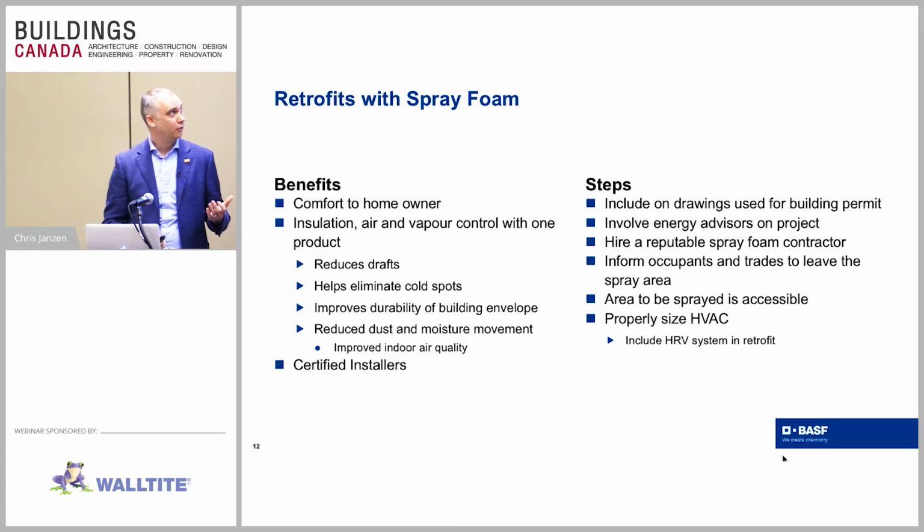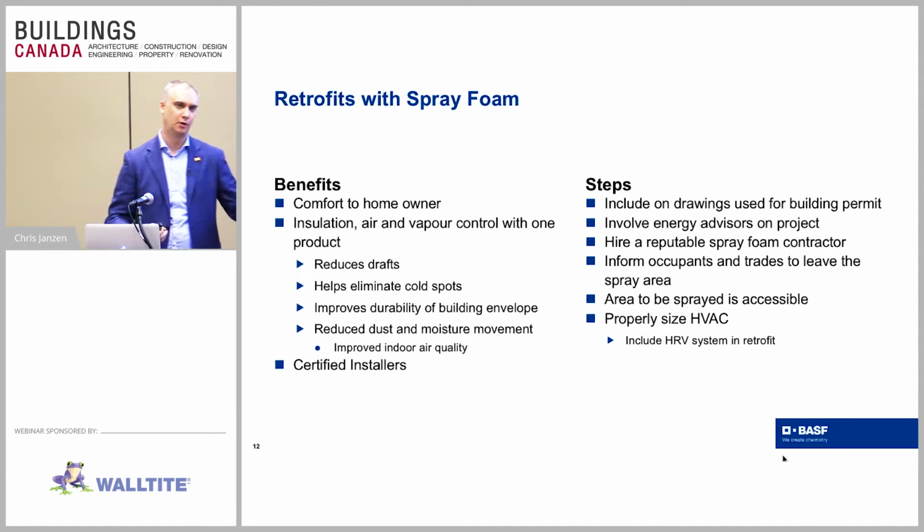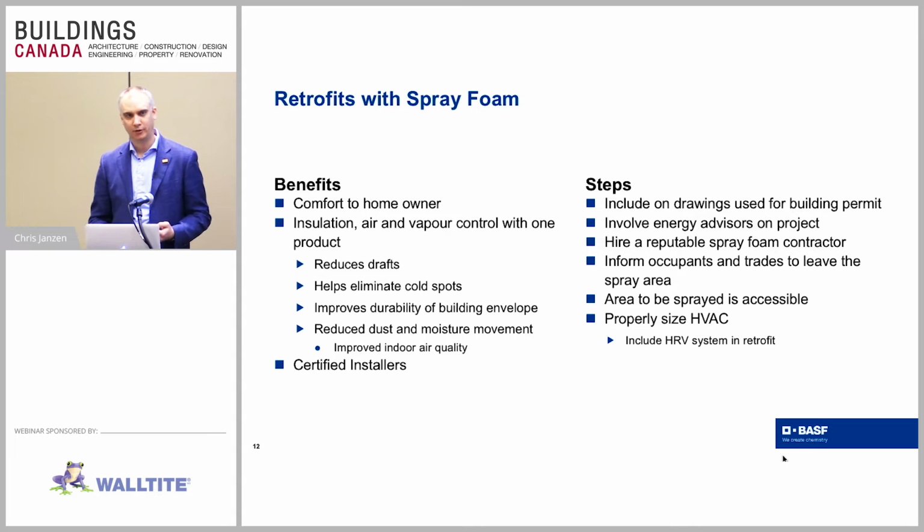Some of the steps that are involved with the actual spray foam application, again, from the design standpoint, from the start of the building project, one of the biggest things in my experience has been make sure that the spray foam is included on the drawings that go for the building permit. As we know, it meets the building code, but a permit official, a building official, when they walk in to do an inspection on the job, if it says that there's bat and poly there and they walk in and they see spray foam, they're going to put their arms up and say, wait, you got to do a new permit application, go back and all that kind of stuff.